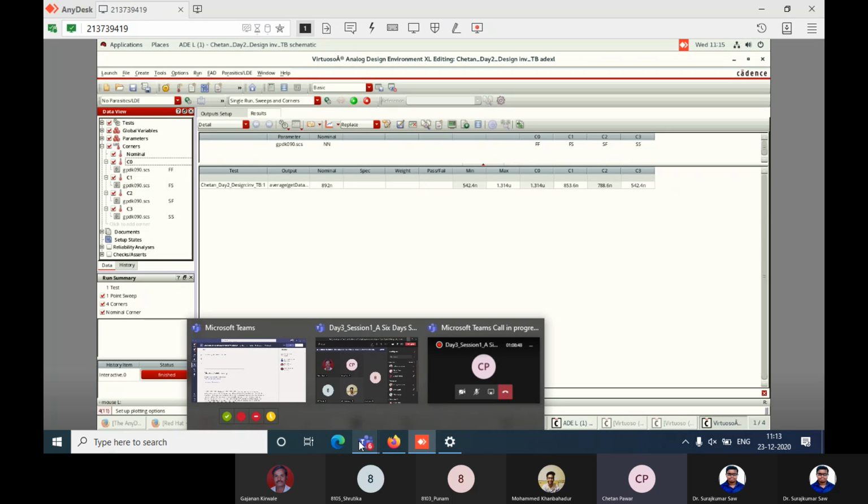All of you, sir has shown you how to do the corner analysis for the power parameter, right? Similarly, there is a delay parameter, with a rising time delay and a falling time delay, right? First you calculate those delays in ADE.